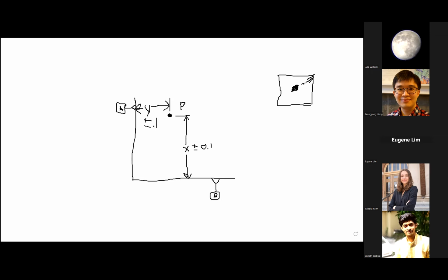So if you follow me here, under this dimensioning and simple tolerancing of this point P, we constrain this point, but we have situations where we might have this point move all the way to the corner of this box. And if you do a little bit of trig, that's a square root of 2 times the tolerance, which is more than just this tolerance alone.